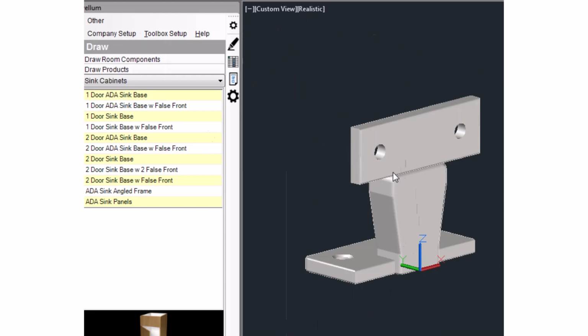And so I've got this drawing that I downloaded from my hardware manufacturer, and I brought that in. I've scaled it to my current units, and so for a metric configuration, I'm going to leave this outside the database, and so I'm going to leave it in metric. And for an imperial configuration, I'm going to set it up in imperial, but in this case, I'm going to work in metric. So the X and Y origin for this piece of hardware is always going to be the point at which I'm going to place it, and then my hardware machining is going to be oriented from there.